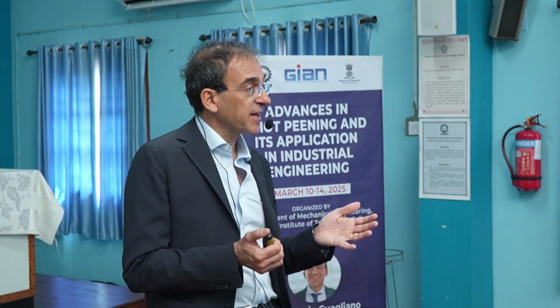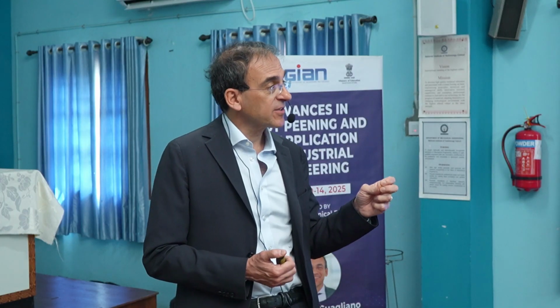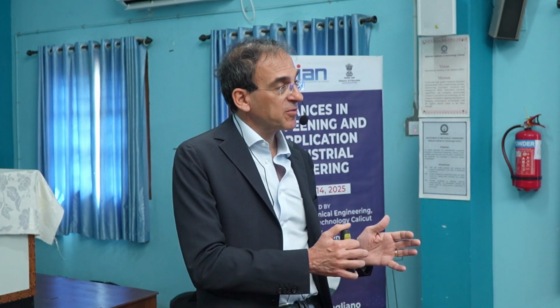That is quite accurate. Indeed, we consider not only the part itself, but also the main point is that we are choosing the parameters, the shot, the intensity, the coverage, as a function also of the working condition, of the service condition. And this can be done, why? Because we can control the way shot peening is performed. So we can relate the expected residual stresses to the applied stress, and then we can develop the so-called optimal shot peening treatment.